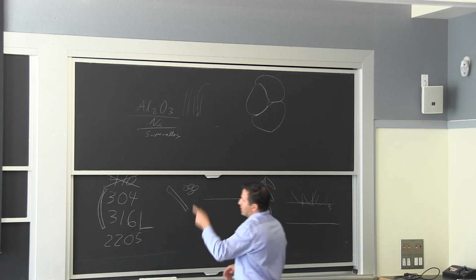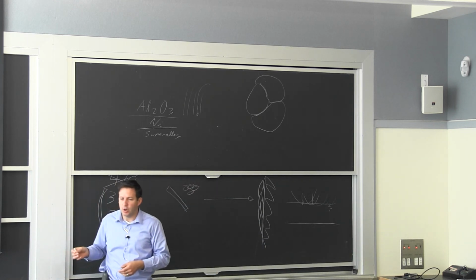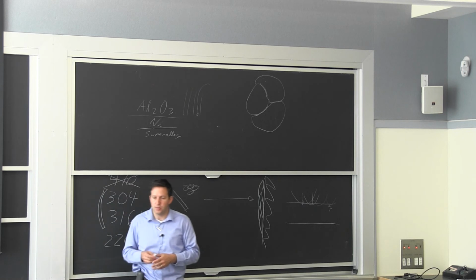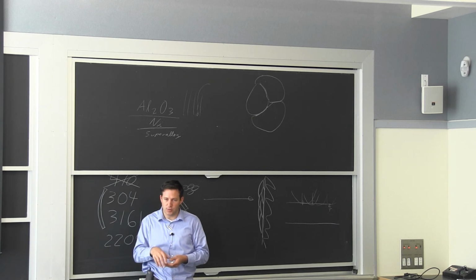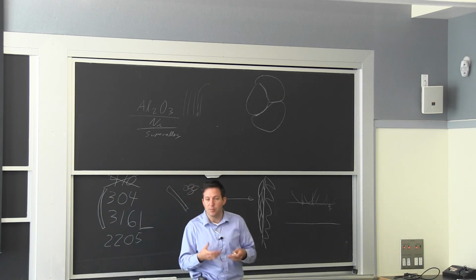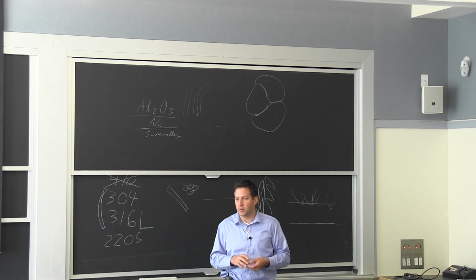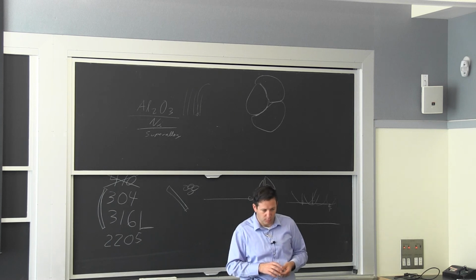So the other surface treatment, the one we talked about a lot because it was tied into all our heat treatment, was to diffuse nitrogen or carbon into the surface of the steel, and then go through the heat treatment to make a very hard surface layer. And that's very typical of self-drilling fasteners, which is one example that we went through together.